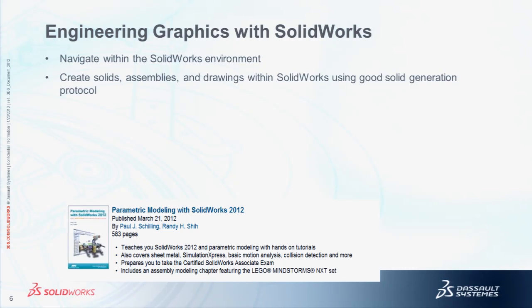So how do we kind of instill this idea about how you're going to make the solid? And I always like to start with defining the features of the part. So, get your hands off that keyboard and mouse and let's put up this part and let's talk about what are the features of the part. Okay, I've got maybe an outside perimeter. Now maybe I've got a threaded hole, a through hole, a boss, whatever. Let's define what the features of the part are.